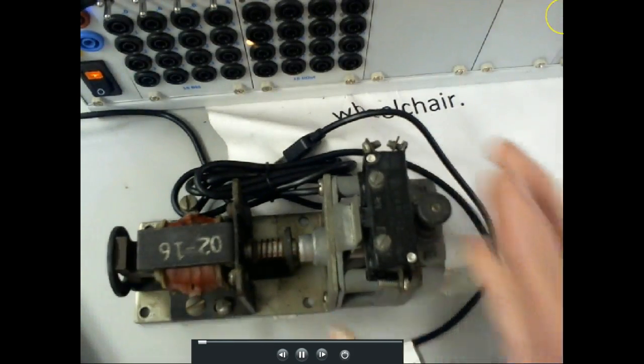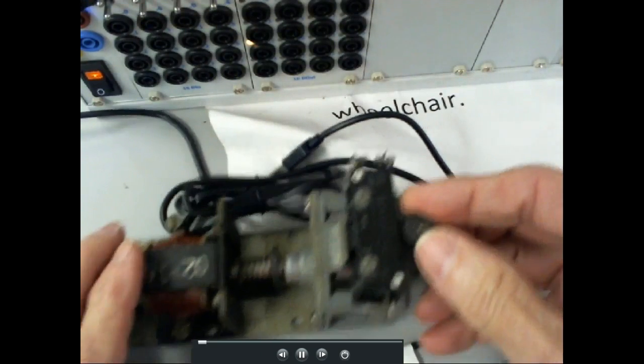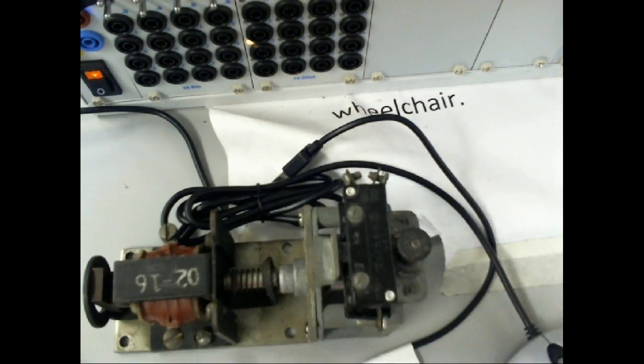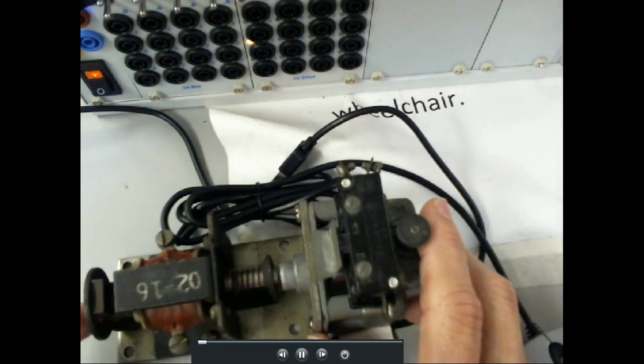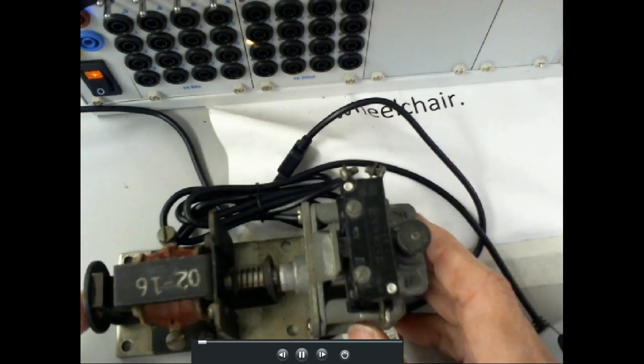So this is a dashpot timer. So this is my timing element right here. This is where I adjust the time. So all you're doing is adjusting the orifice between the two diaphragms. Does that make sense? So how fast can the liquid flow from one side to the other, which would be the time. And so this is my relay. So this is an on delay timer. I'm sorry, this is an off delay timer.